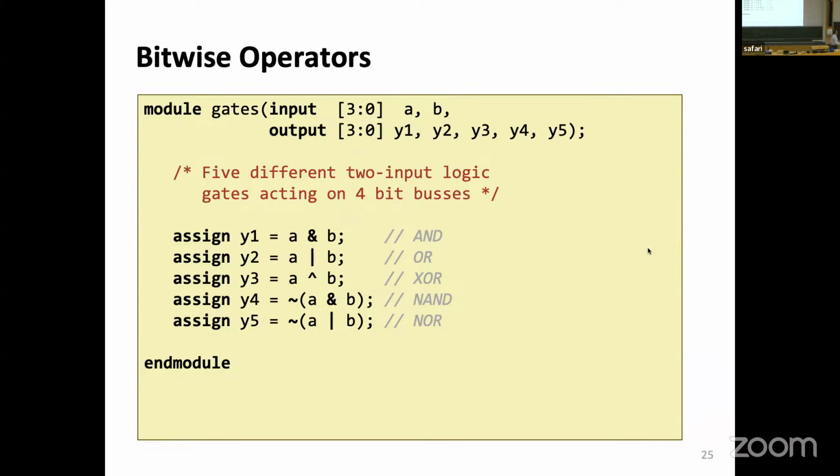So let's first discuss the XOR. The OR function is 1 whenever one of them is 1. And if both of them are 1, the OR is still 1. The exclusive OR says up to here it's the same, but only one of the signals can be 1 at a time. So when both of them are 1, the output of the XOR is 0. And then it's the inverse. Well, that's simple, right?